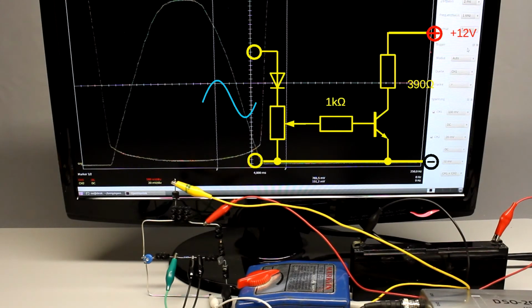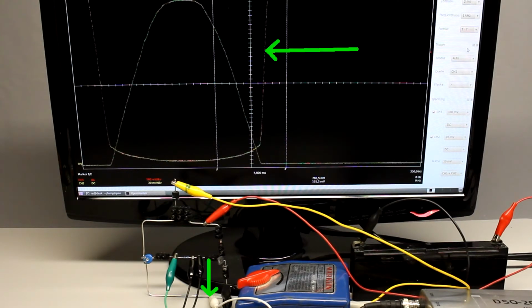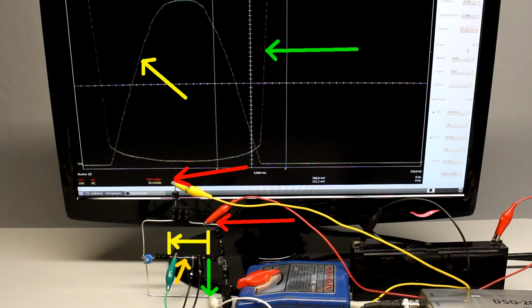By using a 2-channel oscilloscope operating in XY mode, the curve progression of a transistor can be recorded quickly. One channel is used to measure the voltage drop at the base pin, the other one to measure the current running through the device. Once more, the base current is recorded indirectly by measuring the voltage drop at a series resistor. A battery supplying a constant voltage is connected to the output circuit of the transistor. An AC transformer is connected to the transistor's input circuit.